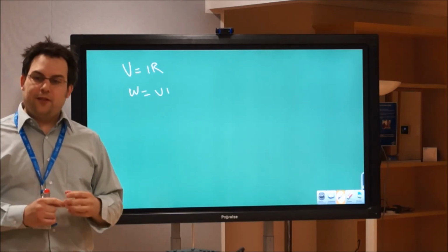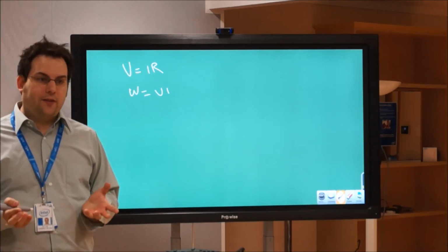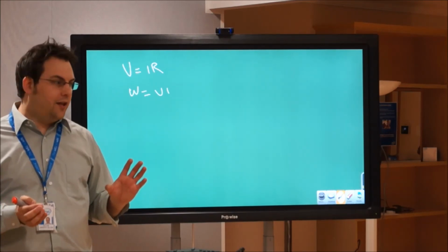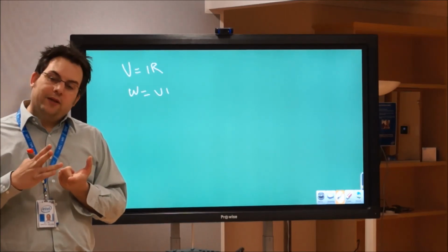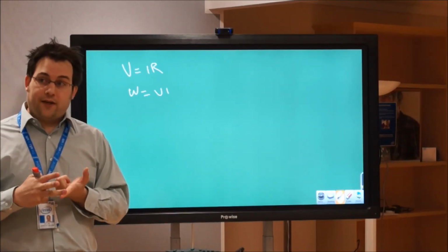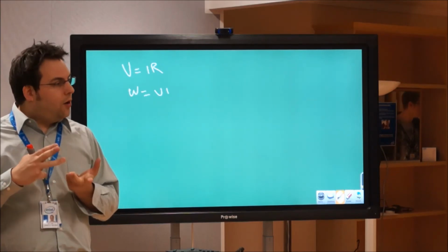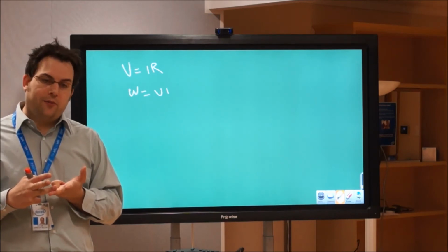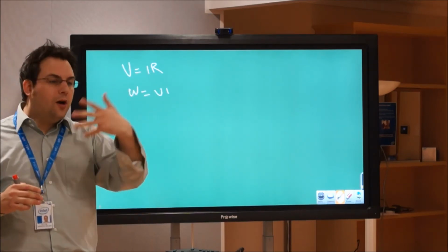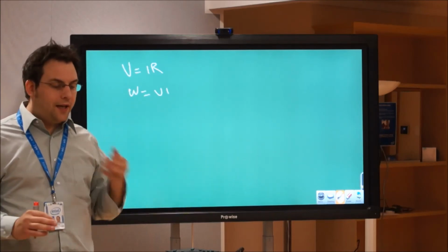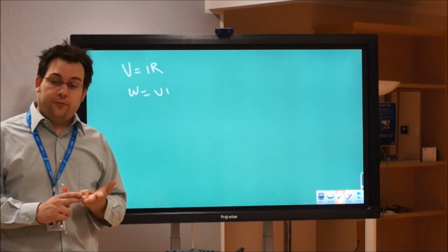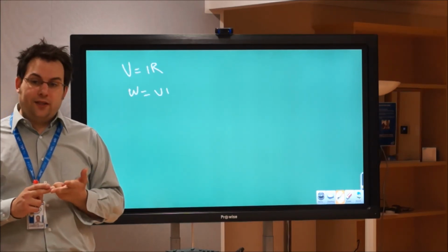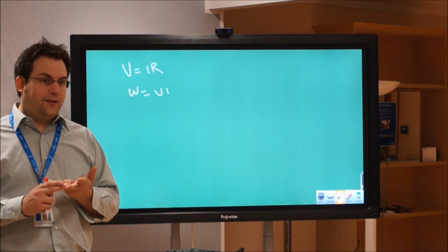Well, if you're on a desktop machine, you can most likely change a couple of settings. You increase the overall turbo power, so that's the maximum instantaneous power it takes, and also increase the long-term turbo power, which is what it would run at indefinitely, but also the current. So you might need to increase the current you're giving the processor.